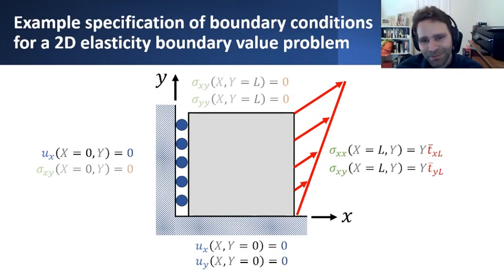Suppose I had this block, as shown here, where it's just a two-dimensional problem to make things a little bit easier, and there's a different number of boundary conditions that I'm applying in different combinations. Along the bottom edge, I'm choosing to prescribe both components of displacement, in the x direction and in the y direction, along that entire bottom surface.